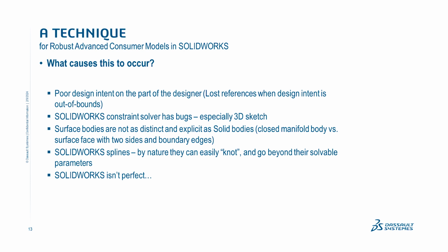Part of the problem is SolidWorks' fault. The constraint solver has bugs, especially the 3D sketch solver, which from my understanding working at SolidWorks is a different solver than the D-Cubed solver, or whatever solver they use for 2D sketch. Also, if you think about it, and I know Ed Eaton goes into this in a lot more detail, surface bodies are not as explicit as solid bodies.